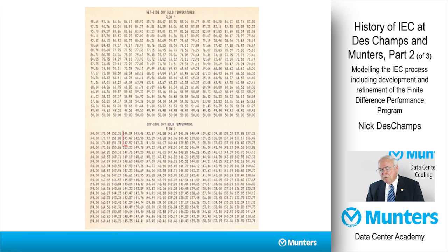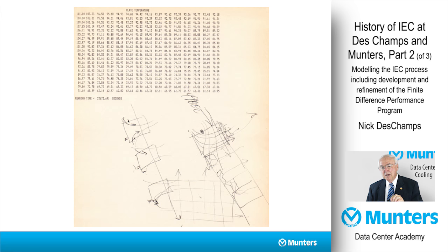So we've worked on it for a good while, but what we ended up with in this figure is we could print out all the temperature changes on the dry side of the indirect evaporative cooler and the wet side, and any other characteristic in that element, which allowed us to determine water temperature as the water flowed through the heat exchangers, the moisture content, the performance. We could nail it right on the head.